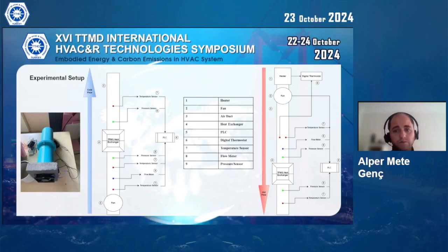And actually, as the working principle of the mono units, warm stale air is extracted and flows through the regenerator, or regenerative exchanger, and transfers its energy to the heat exchanger. As the ceramic heat exchanger warms up and the unit switches to supply mode, clean cold intake air flows through the regenerator and absorbs the accumulated heat.